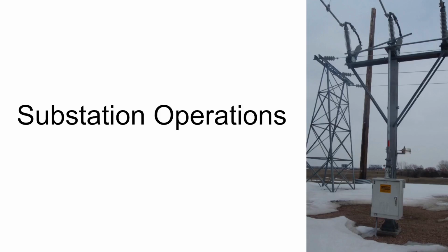One reason you might want to do this is to shift which power conducting lines in the substation take power so that utility personnel can conduct maintenance on equipment, or because equipment on a powered circuit experiences a casualty and the utility wants to maintain power for their customers. The operator can also track the state of locally operated manual switches based on reports from field personnel. The remote operating station also tracks alarm conditions such as availability of power feeds, state of circuit breakers, and loss of power to the customer.